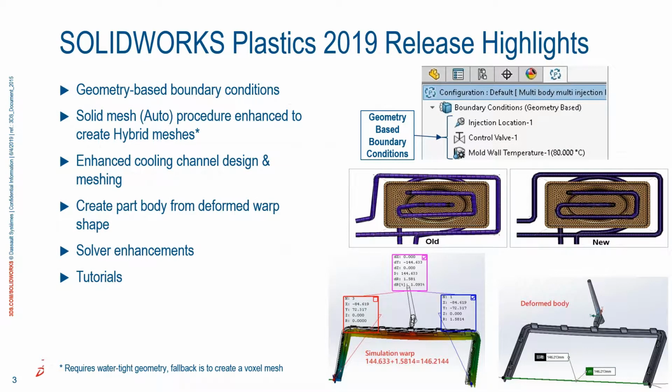Some of the highlights from the latest release of SolidWorks Plastics, just to give you an idea of what we've been working on. You see the bullet list on the left-hand side of the screen: geometry-based boundary conditions. One of the unique advantages of a package like SolidWorks Plastics is that it runs fully embedded inside of your SolidWorks CAD environment. That allows us to do some unique things you wouldn't be able to do in a standalone simulation application, and one of those is geometry-based boundary conditions.